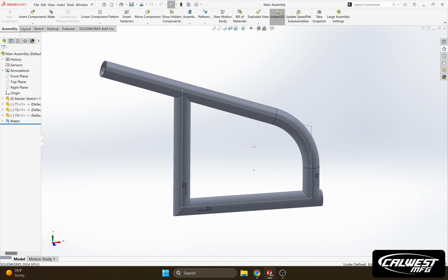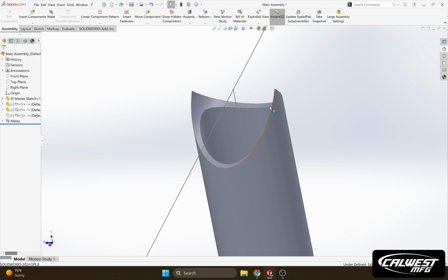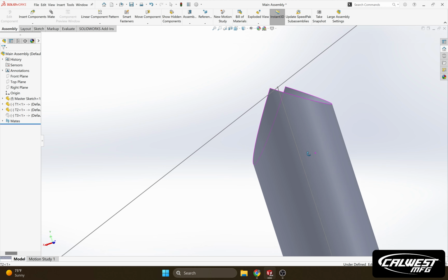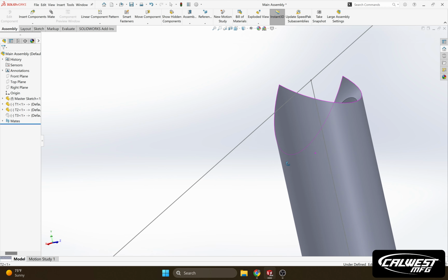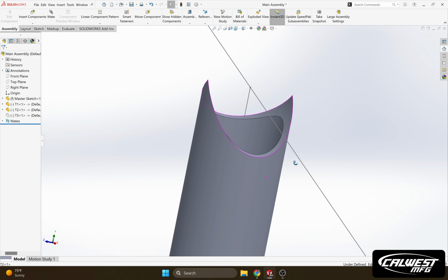So we're back here now with an assembly that's fully notched, and as you can see, it's notched as if we did this on a saw or we used a hole saw. This is how that notch would look. But because we are not going to be cutting it with this curvature here, we're going to be cutting it as if the laser is always looking down on the outside of the tube, and as it rotates, it's going to be cutting. So we're going to get what's called a normalized cut, or a perpendicular cut to the surface.